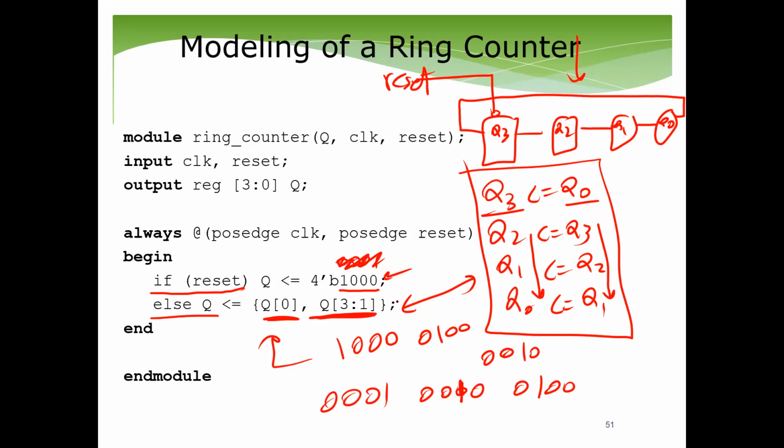Second important thing about ring counter is to know what you are resetting to, because if you reset to all zeros, it will not work. Okay, that's it for the ring counter.